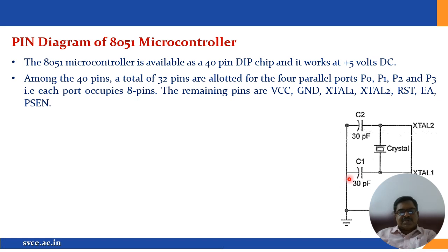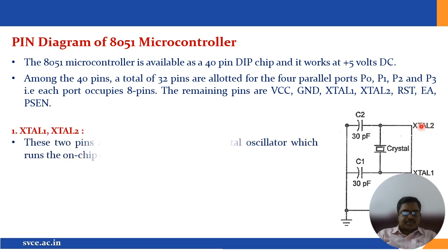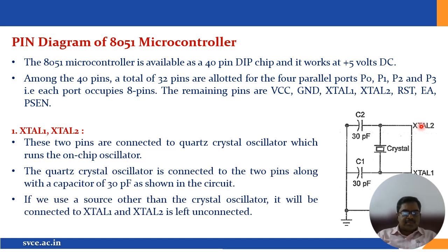And here you can see the quartz crystal connected to XTAL1 and XTAL2 through capacitors. Using capacitors, the oscillator is connected through XTAL1 and XTAL2. So 30 picofarad capacitors are used in the circuit.